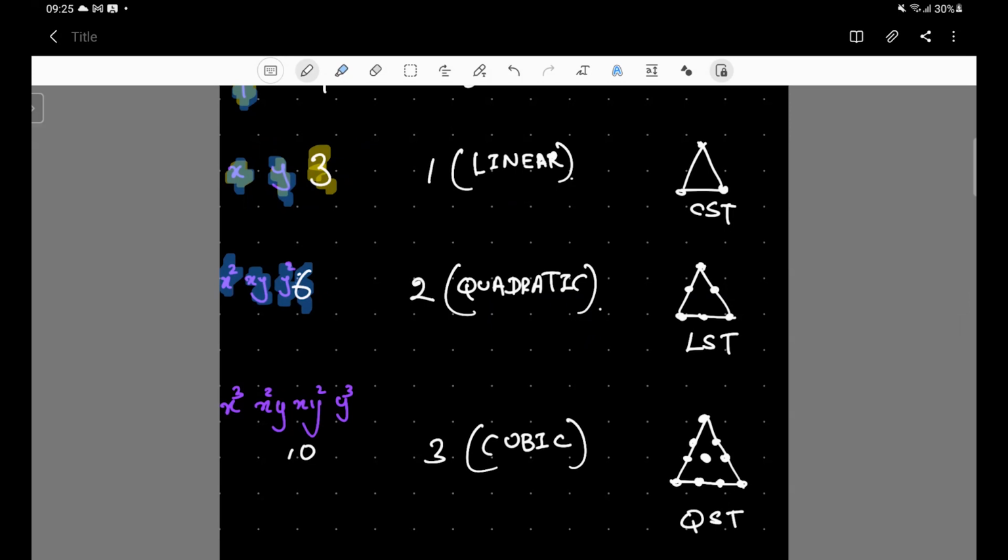What I wanted to highlight from this is that whenever we use more sophisticated elements, the number of degrees of freedom tends to increase, and we can also use high degree shape functions, high order polynomials, to describe the displacements accurately, especially when there are rapid changes of loads, rapid changes of strains, changing of the material, and changing of the boundary conditions.